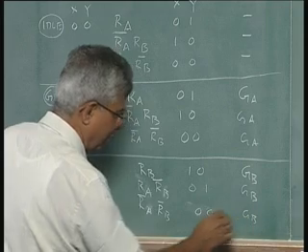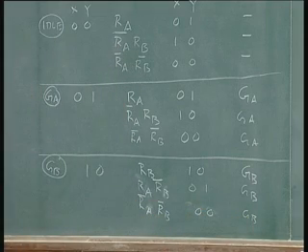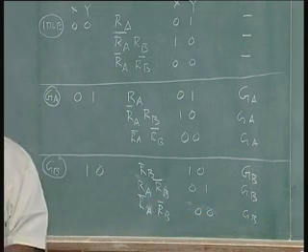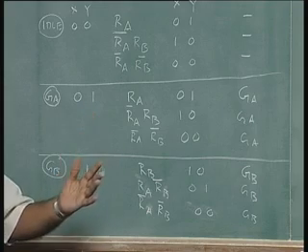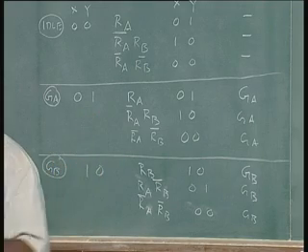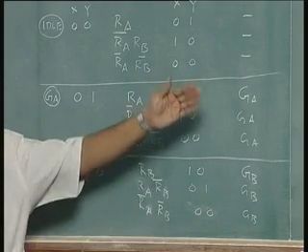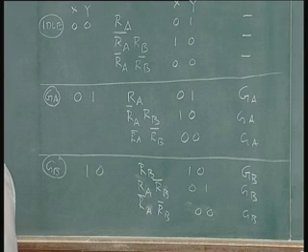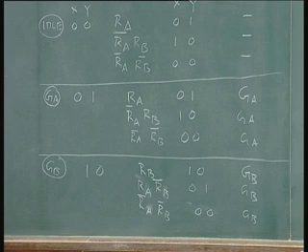Again, conceptually this is not different from a state graph. ASM is not conceptually different from state graph. This table is not conceptually different from state table, but the way in which you write is slightly different so that it can directly be implemented. This is drawn this way so that we can have a direct correlation with the hardware that we have in mind. Signals come, the transitions occur based on signals, outputs occur based on signals.